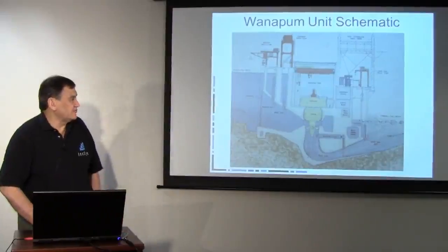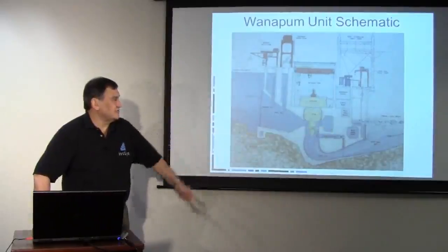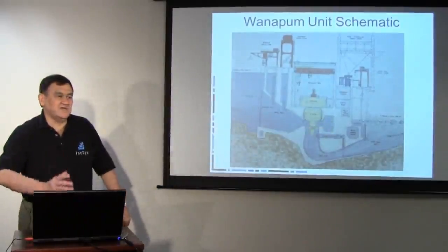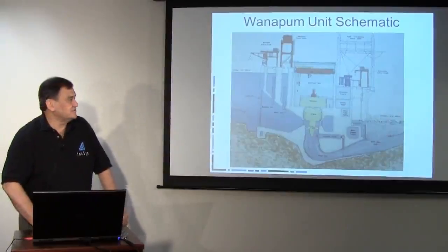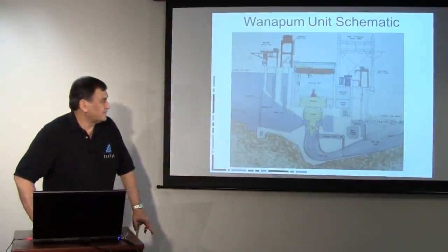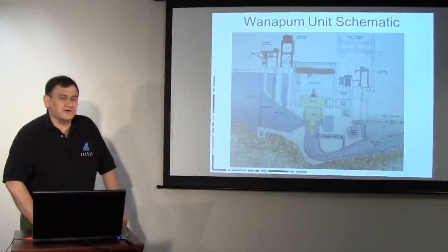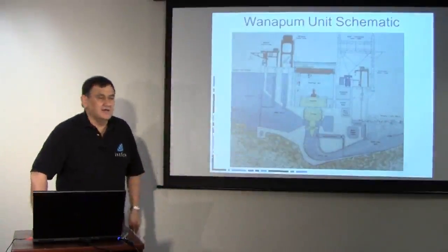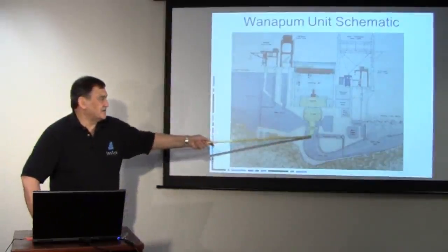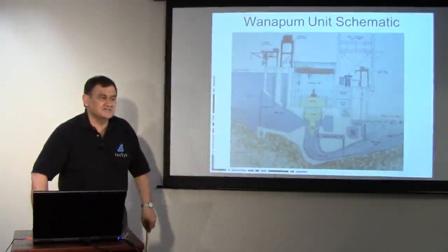So the power plant operators clearly want to stay away from those particular power outputs that cause the cavitating effect. I was actually down right next to the scroll case when Bob took that into a cavitation zone, and the vibration and the noise were really huge. The other aspect you have to worry about is that we have to allow the salmon to come through here, and clearly the cavitation can cause damage to the fish.